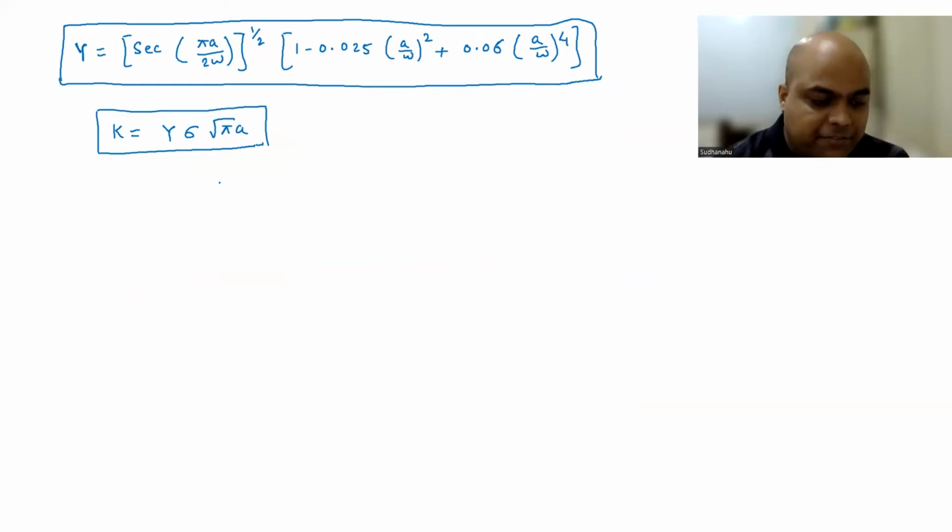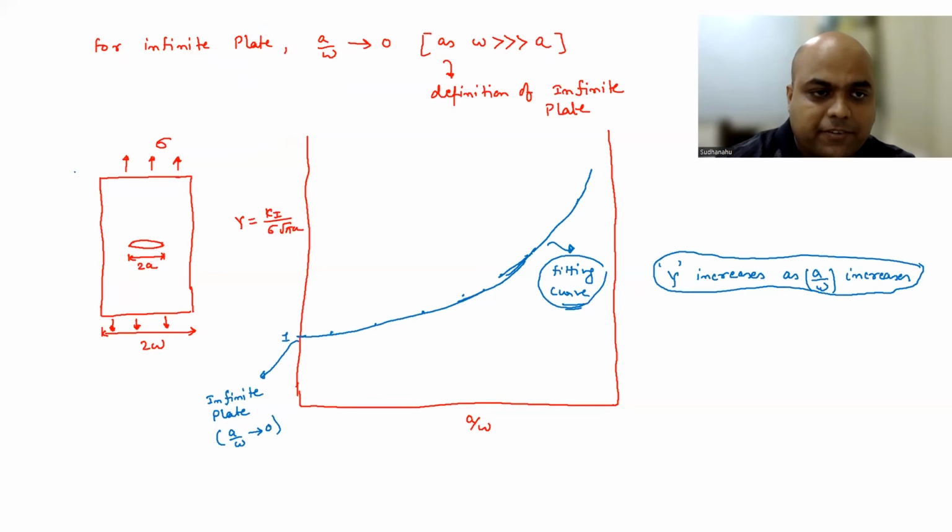Now for this particular configuration, what is sigma? Let's talk about load, because typically we have the load and then we can calculate sigma if we know the area. Remember, sigma here is the far field stress. If it is under an applied load of P, we know what 2W is, and if we know the thickness B, we can figure out the applied or far field stress sigma.